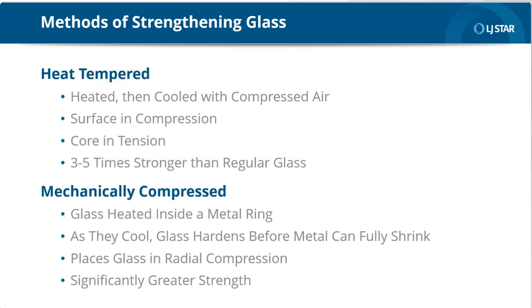Under such strong compressive forces, the glass becomes elastic. Therefore, sight glass windows have a higher pressure capability than sight glass assemblies. Taken to the extreme, a sight glass window will not shatter. When the surface stretches beyond the elastic capability, small cracks may develop near the surface. The subsurface glass is still under compression and can remain in service safely for a short time.